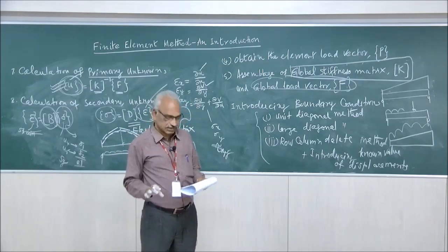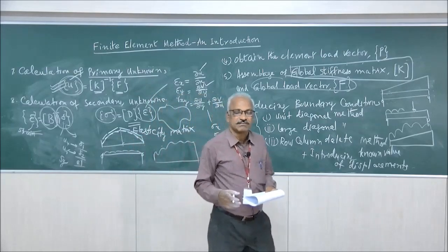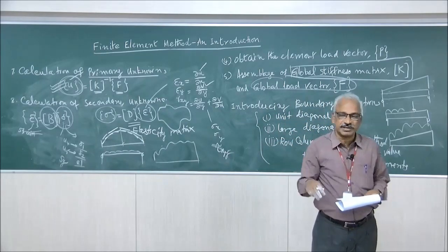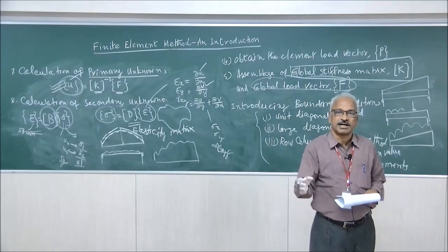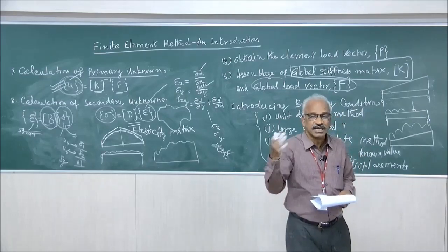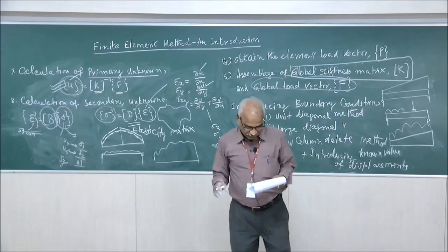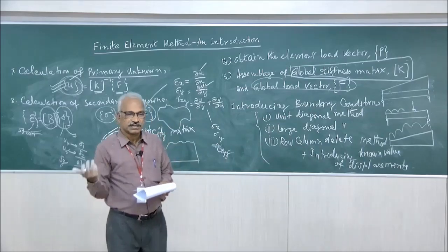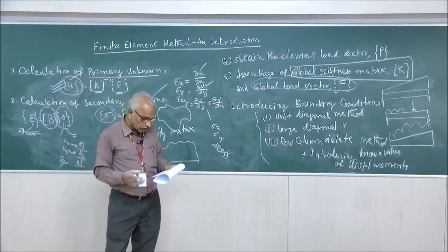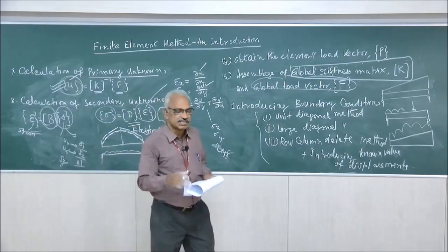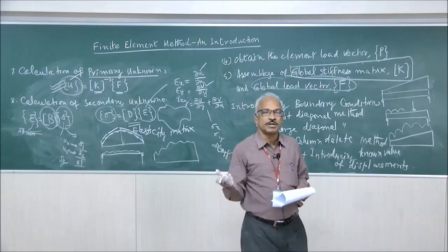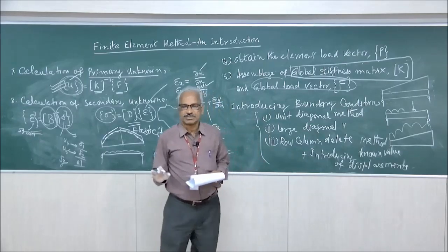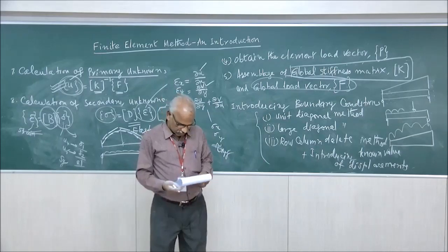So, configurations, element sizes, violent variation in the element size. At one end, you start with a 10 centimeter by 10 centimeter element. At the other extreme, in between, you have 100 by 100. The other extreme, 200 by 200. If there is such violent variation in the size, it will be difficult. Boundary conditions, if you are not introducing a sufficient number of boundary conditions, then the solution will be difficult. And also units. For dimensions, if you use meter, for stress if you use Newton per millimeter square, for moment of inertia if you adopt millimeter to the power 4 or centimeter to the power 4, then it will be a problem. So you will have to consistently follow the same units.